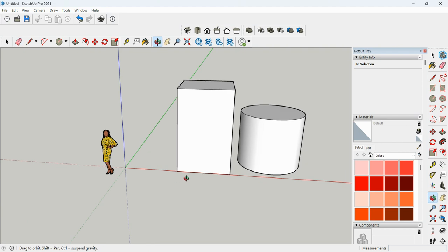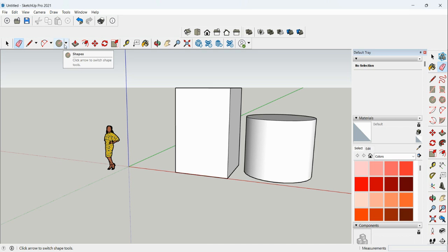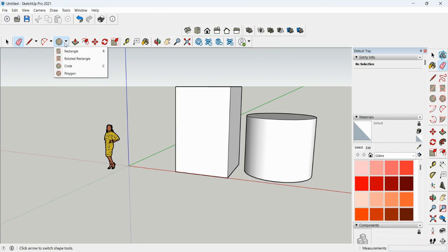So what's next? Let's try to do a polygon in SketchUp. How do we do a polygon in SketchUp? So go here. Go to polygon. Okay, watch closely. Listen closely. Polygon. Now, by default, it has six sides on the measurements right there.